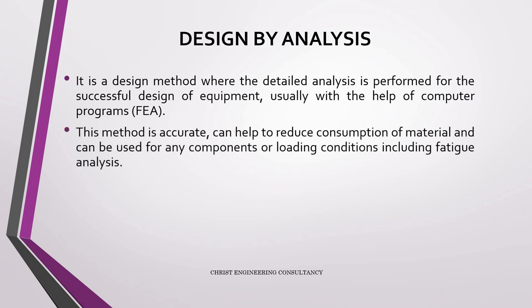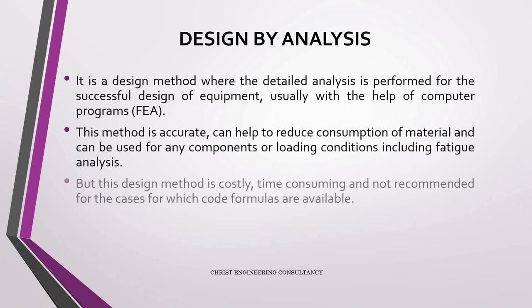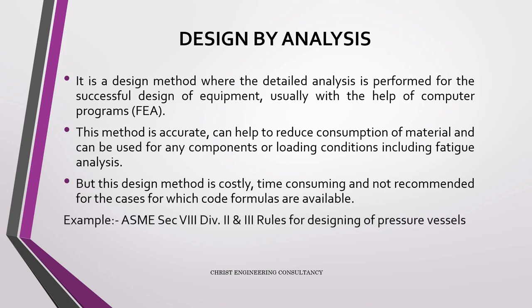This method is accurate, can help to reduce consumption of material, and can be used for many components or loading conditions, including fatigue analysis. But this design method is costly, time consuming, and not recommended for cases for which code formulas are available. In ASME Section 8 Division 2 and 3, design by analysis method is followed.